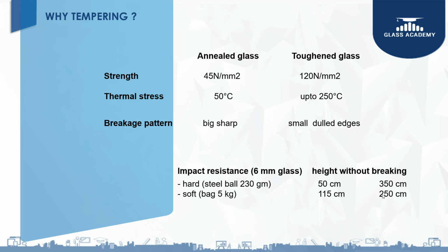Yes. Whatever we have seen here, we will also see all these things in the process plant in our third day. So this is the basic test. What we'll do is we'll have some 230 to 250 grams steel ball, and we'll be placing a glass with some 3 mm from the base. We'll have the front glass with drops from a height of 3 meters, 6 meters and 12 meters, depending upon the thickness and combination of glass.